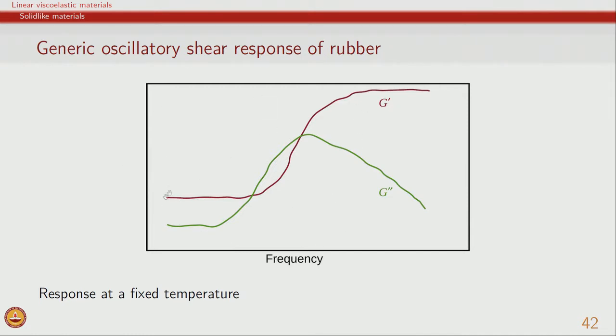What this kind of graph also tells us is that a material at low frequencies is a reasonably soft material because the storage modulus is much lower. Also it is a very elastic material, in the sense that it will regain any deformation that was given; the deformation will be recovered and it will regain its shape, and so this is the quality of rubber. But the same material, if examined at much higher frequencies, will appear as a fairly hard material with a very large storage modulus, and this material may also be brittle. And so we have a rubber to glass transition, or a transition from a soft, flexible material to a hard, stiff and brittle material. And clearly we have already discussed that there is an equivalence between the time response of the material and the temperature response.